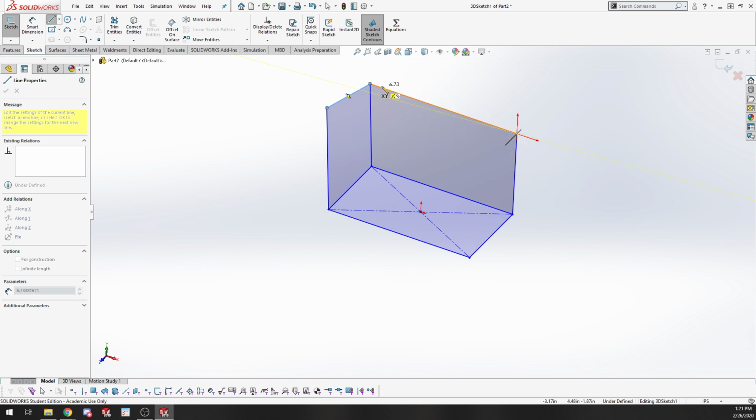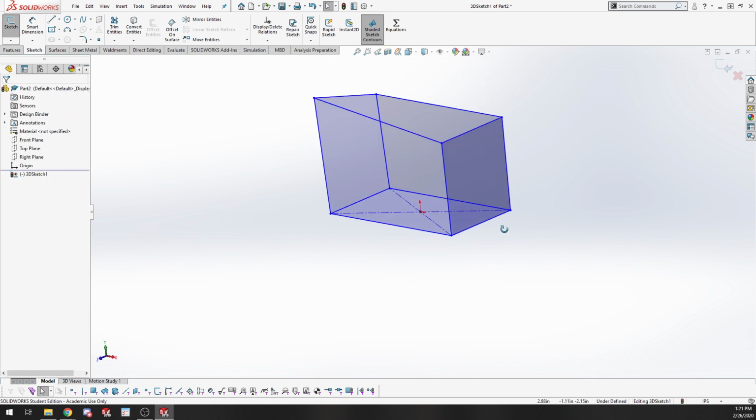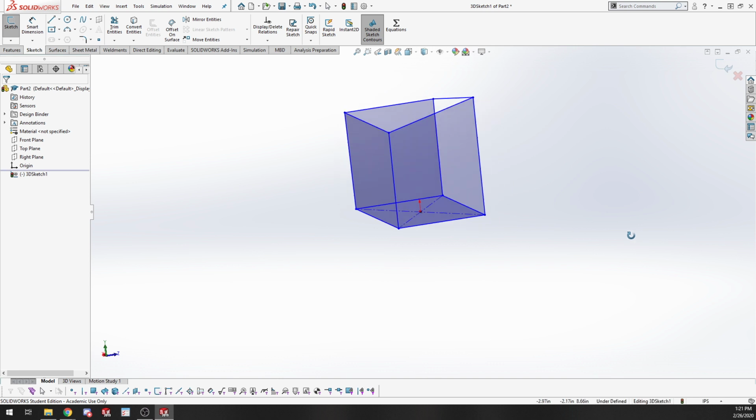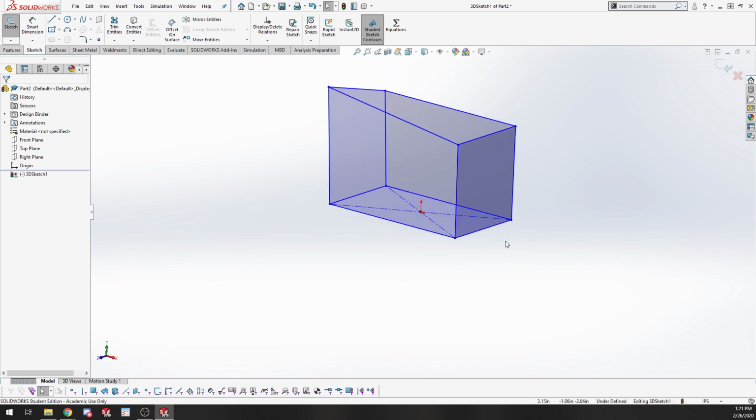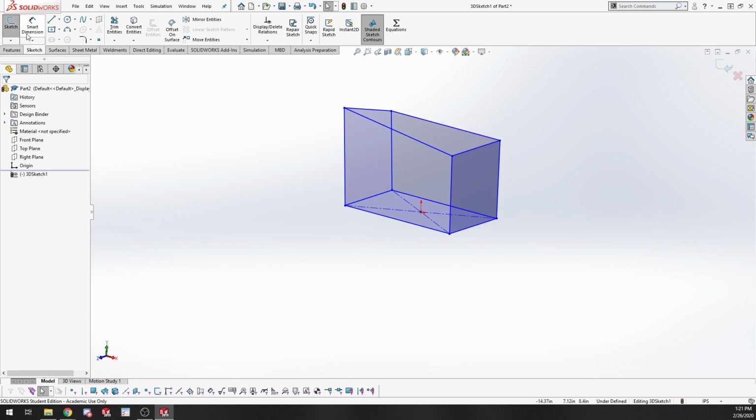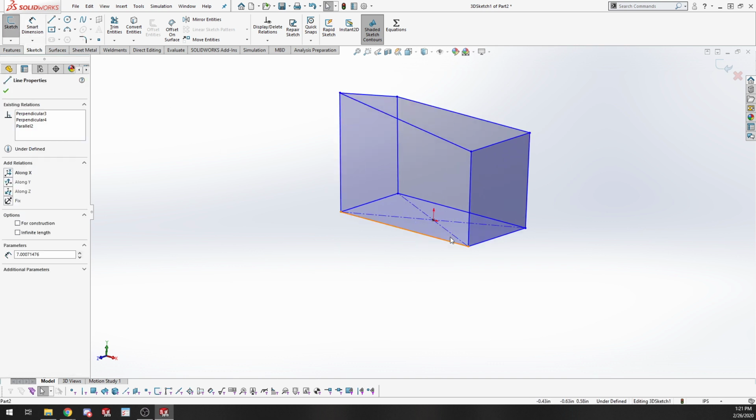Right now, though, it does want me to draw kind of along that back face, so I'm going to tab out of that and go this way. And then one last line to connect those two. All right, and you'll notice that everything's kind of skewed because it's very hard for SolidWorks to think in a lot of different directions and kind of match up parallel stuff. So we usually have to go back in and add in kind of those vertical and horizontal stuff at the end.